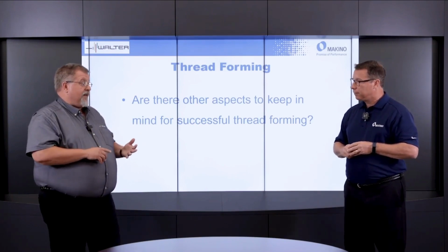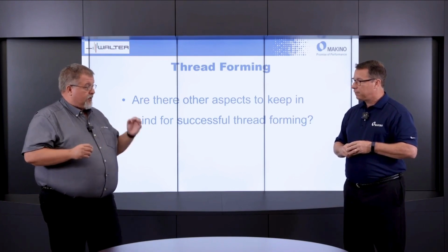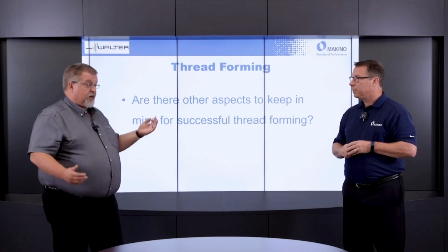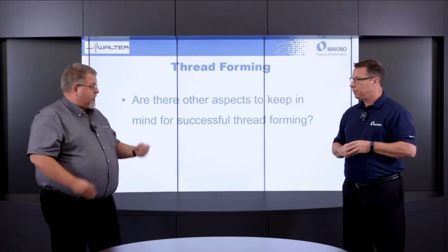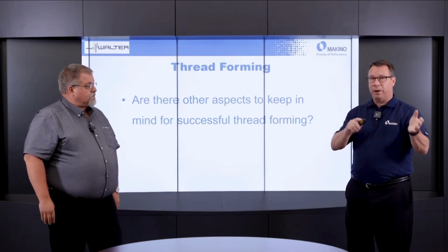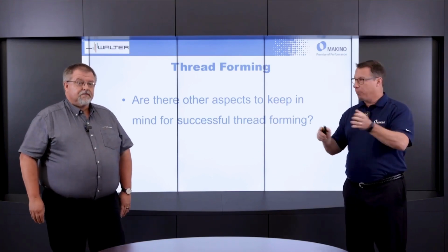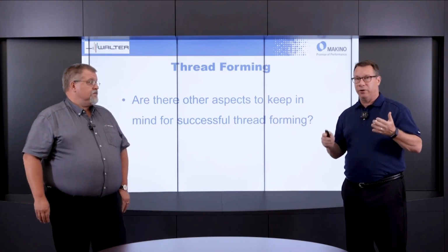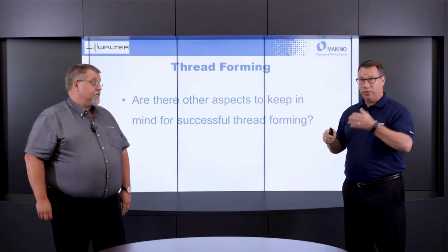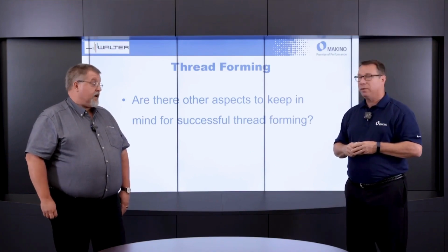And the best place to find the correct tap drill, ours is engraved right on the shank. Most premium tools will be something similar, very easy to find that information. Yeah, so if you're thinking about experimenting a little bit in your shop, to Brian's point, just make sure you're using the right size drill to create that hole prior to the process that you select to make the threads. Exactly. All right, thank you.